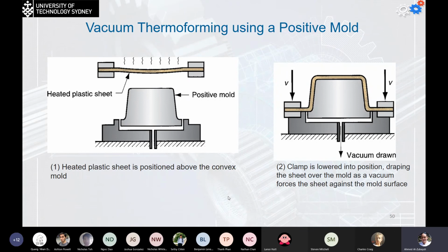If I'm going to use it to make a smaller number of parts, then the old method usually was using wood. They cut the wood on the milling machine to make different shapes. You know that wood is porous, and this will make the plastic stick on it, so usually they put some varnish on top to give it a glossy finish.